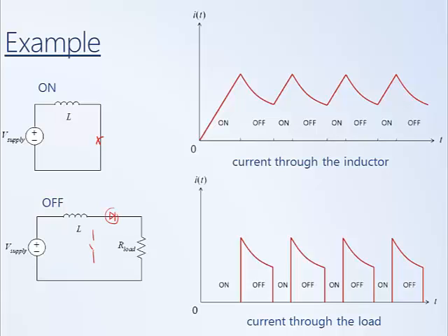The way that that is achieved in reality is with the addition of the capacitor. So the idea is that when the switch is on, there is still current flowing through the load, and where that current comes from is from the capacitor. The capacitor stores charge, stores energy, which is then released when the switch is flipped. And so in reality, we'll get a much smoother looking kind of output.